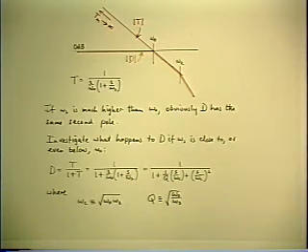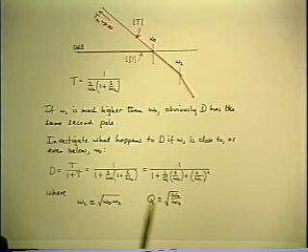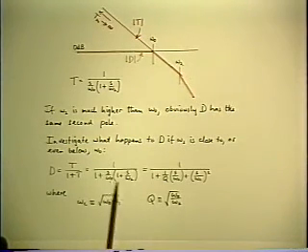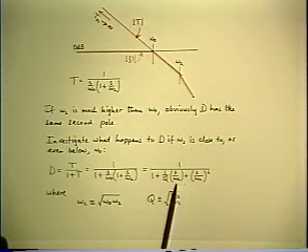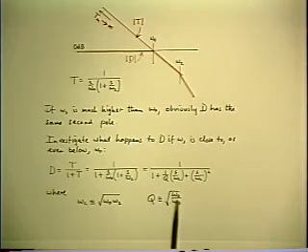And now you should have that automatic response. Whenever you see a quadratic, find its corner frequency and its Q factor. So write it in the normalized form, and in order to do that, you have to define the corner frequency omega c as the square root of omega 0 omega 2, and the Q factor as root omega 0 over omega 2. That's exactly the same quadratic that we spent a lot of time talking about in relationship to an RLC filter.